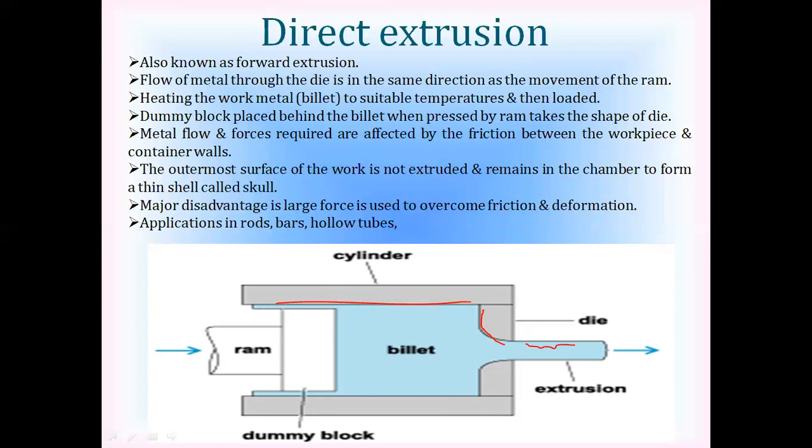If you observe carefully here, the diameter of the dummy block is very less when compared to the diameter of the container, which means when the dummy block is being pushed with the help of a ram, you can see here the billet is being extruded.